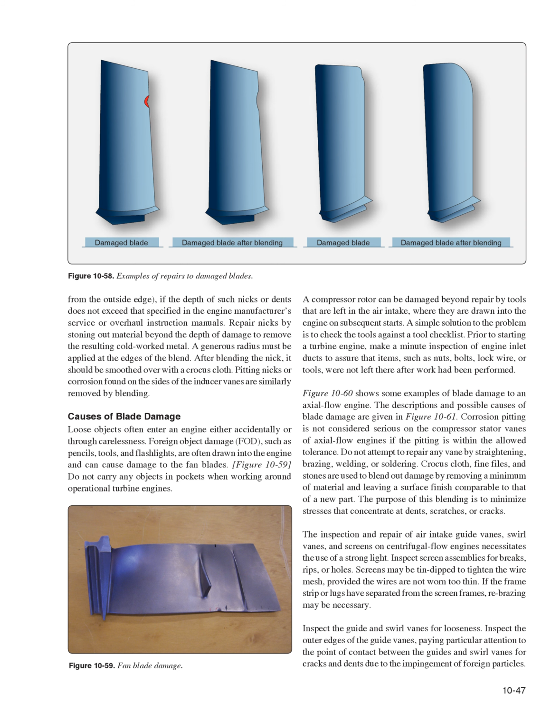Corrosion pitting is not considered serious on the compressor stator vanes of axial flow engines if the pitting is within the allowed tolerance. Do not attempt to repair any vane by straightening, brazing, welding, or soldering. Crocus cloth, fine files, and stones are used to blend out damage by removing a minimum of material and leaving a surface finish comparable to that of a new part. The purpose of this blending is to minimize stresses that concentrate at dents, scratches, or cracks.